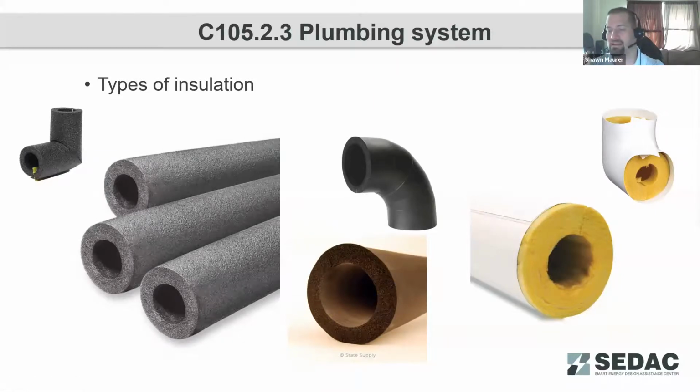What we want to highlight here is that where you've got angles or joints, T's in that insulation, you're going to want to form those joints with miters so that you're not putting additional stress on this insulation, which may compress it and thus reduce its R value, or put tension on it, which would also compress that insulation in the tension spot, reducing its R value, but also put additional stress on it and cause that insulation to wear out faster over time. So that material will start to pull apart.